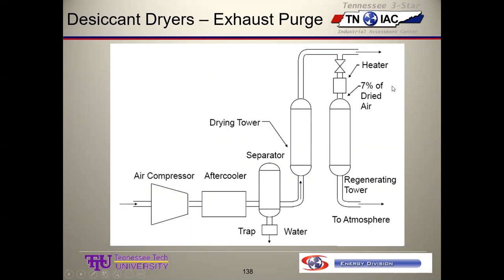So if we had a 1,000 CFM compressor and 1,000 CFM dryer, that would be what, 70 CFM. So 70, that's 0.7 times 20 if it was 20 kW. So that's 14 kW for the compressed air times, say, 7,000 hours times 0.08. So that's down to like $7,800, but I got to pay for the heater energy too.